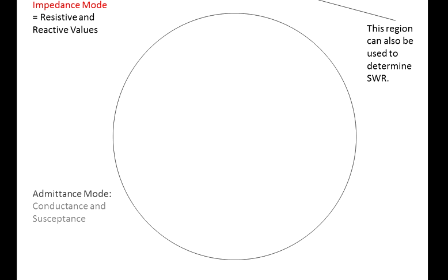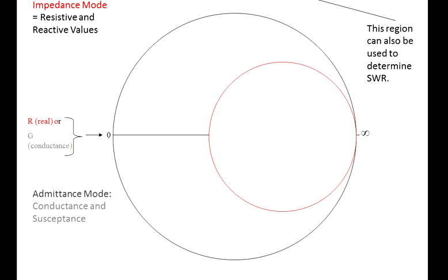So you can actually build your own Smith chart by starting with a circle. Draw an axis down the center. The axis will be where all the resistive values originate from. It's scaled from 0 to the left to infinity on the right. If you start at the center and draw a circle, you've now characterized on that circle every potential reactive component value that's associated with 50 ohms, or the normalized value of 1.